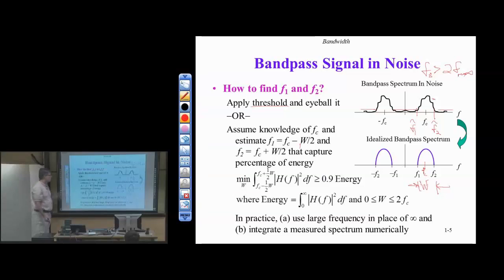I would suggest in homework 0 to eyeball it. It's good enough. Why does it give you a negative left edge? Because there's so much frequency content left and right of this. It picks up all that as energy, and I just have so much more spectrum out here that it throws off the value of capital W.